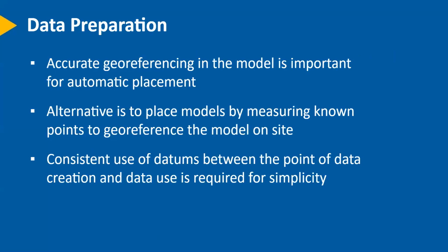Another consideration to make when doing data preparation is that many CAD models, especially of standalone infrastructure, are not always georeferenced. So either those models need to be georeferenced in the office, or the augmented reality solution needs to have the ability to measure or georeference models in the field. So there's two methods there: the pre-georeferenced or the ability to georeference it in the field.